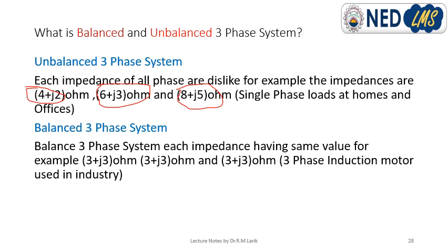That's why we use neutral. We need neutral for that. And what is the purpose of the neutral wire? The purpose of the neutral wire is to return the current. It flows from the line and comes back through the neutral. Neutral gives the return path to the current. You know, current will flow in the mesh. When the loop completes, the current will flow. When the loop is incomplete or disconnected, then the current will not flow. So the neutral is to complete the circuit.